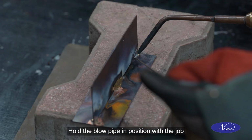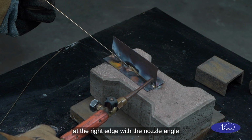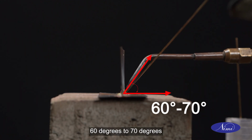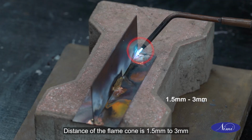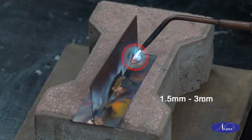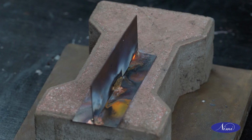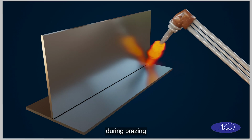Hold the blowpipe in position with the job at the right edge with the nozzle angle 60 degrees to 70 degrees with the welding line. Distance of the flame cone is 1.5 mm to 3 mm from the surface pointing leftward. Concentrate the flame towards copper sheet to reduce heat loss during brazing.